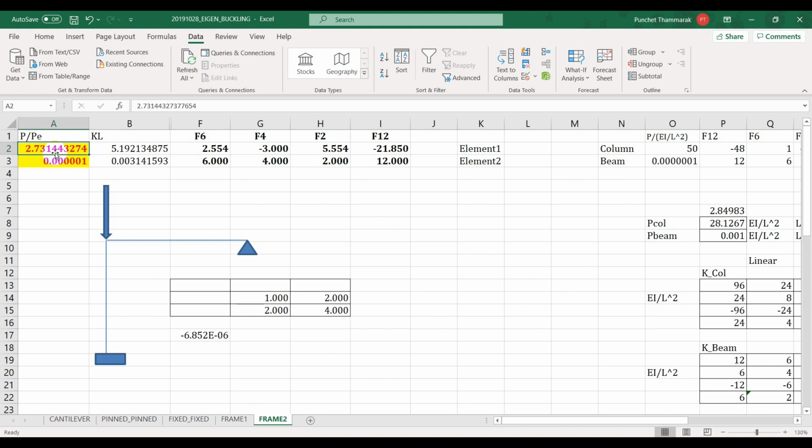You don't need as many degrees of freedom when you use the stability function in comparison with the geometric stiffness matrix. The thing is that as it is computerized, the structural analysis is not done by hand in general. Your software will take care of it. So you will deal with the geometric stiffness matrix more than the stability function. The stability function is not easy to deal with as it has trigonometric functions in there, right?